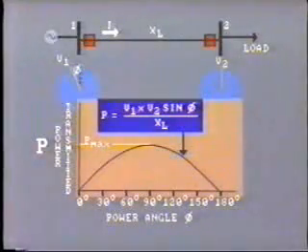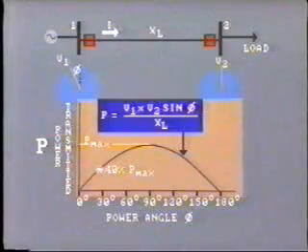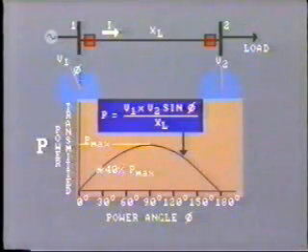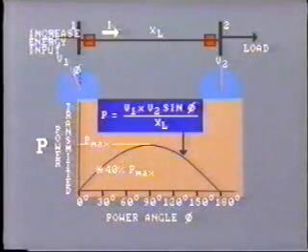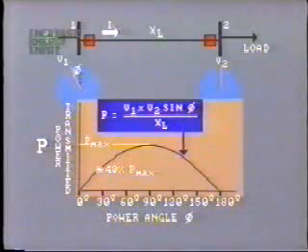Let's look at a simple example. Here, the line is operating at approximately 40% capacity. The load angle across the line is about 25 degrees. In order to increase the load transfer, the operator must first increase the steam input to the turbine by adjusting the governor set point.